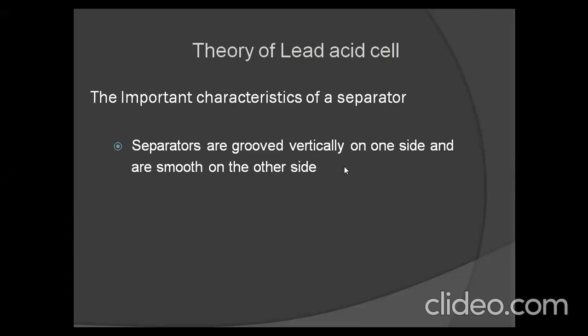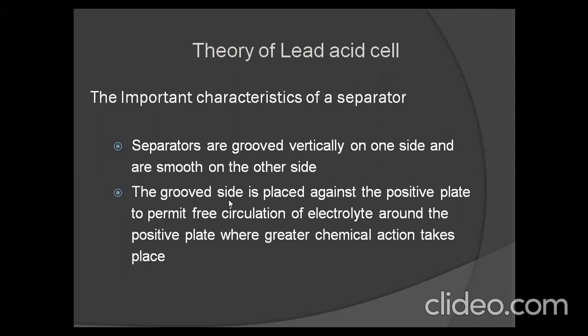Separators are grooved vertically on one side and are smooth on the other side. The grooved side is placed against the positive plate to permit free circulation of electrolyte around the positive plate, where greater chemical action takes place.